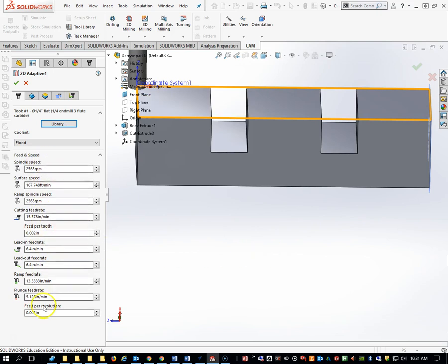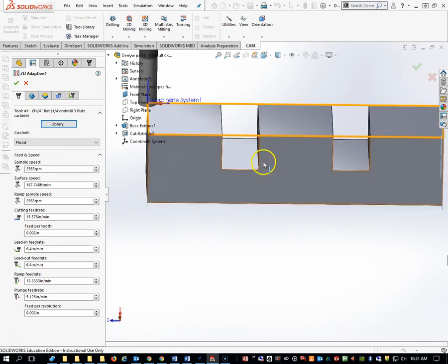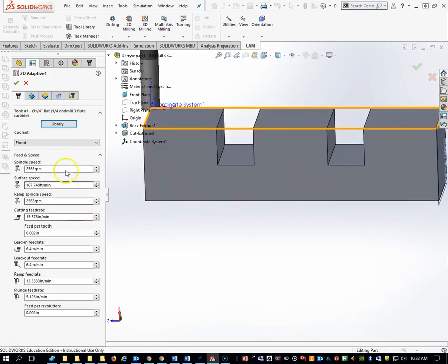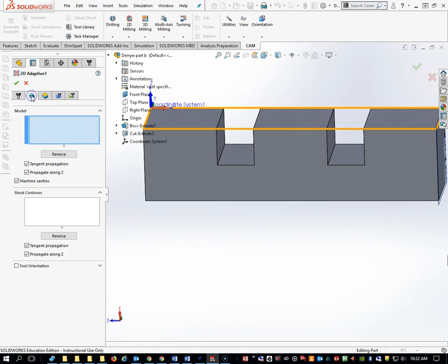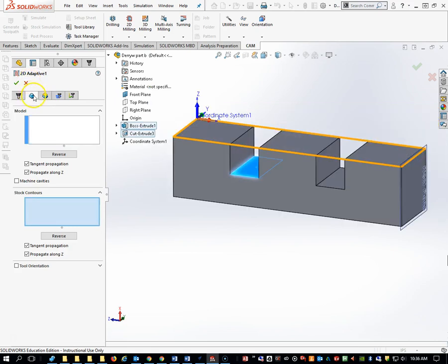We're going to leave these speeds and feeds alone. These are actually ideal for aluminum, but it's not going to take that long to cut these two slots, so I'm going to leave that alone. We're going to go to this guy now. And okay, once we're in here for geometry, we have to decide what we're going to cut and what we're going to leave.